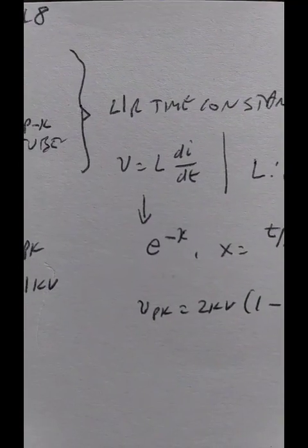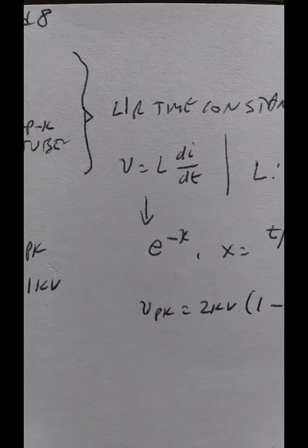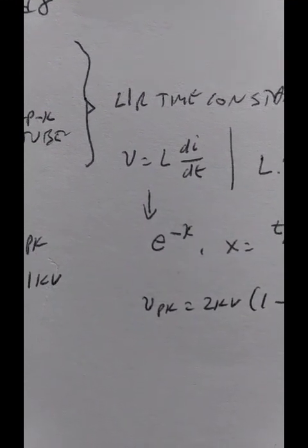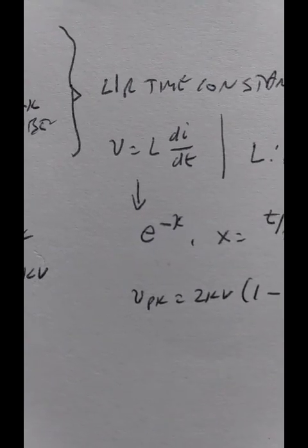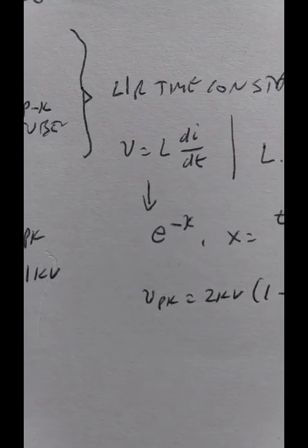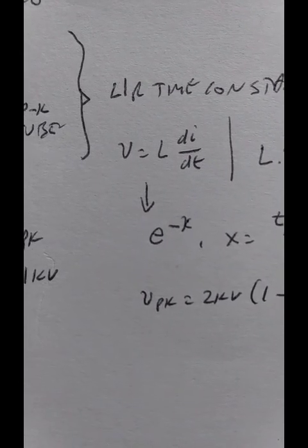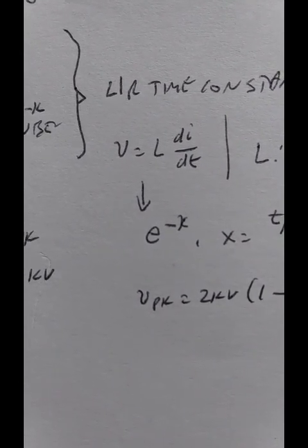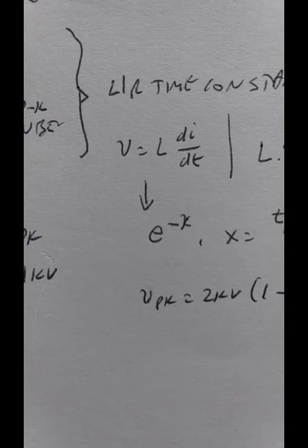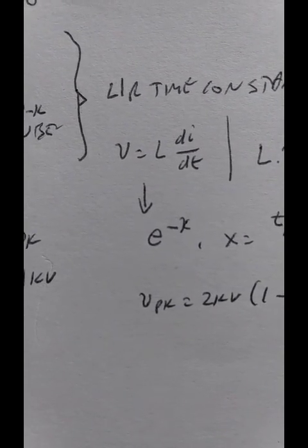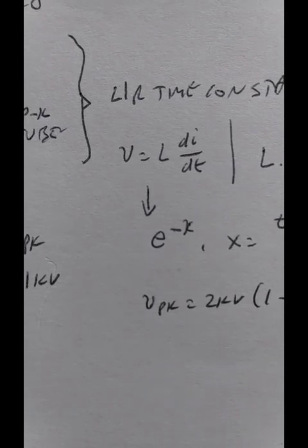The exact answer to how much is the voltage across that inductor when the tube voltage is 1 kV is found by the differential equation. di over dt: if we integrate, time is linear, we just get t, which is time, which is a charge time of 68 nanoseconds. di is exponential. The current is exponential in an LR circuit with an exponential time constant.